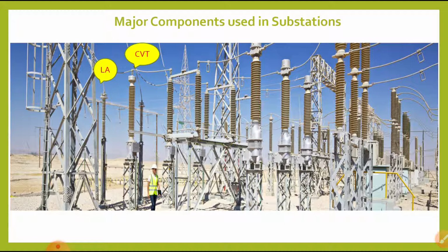Okay. Now after that, you can see another isolator. The isolator, you know, isolates the energized power. Whenever there is no current flowing through the line, we can operate these isolators. We use it for physical isolation. So we cannot operate this isolator under load conditions, as you already know. So that is the purpose of isolators.